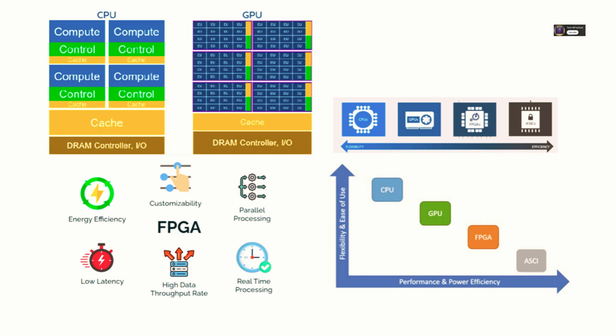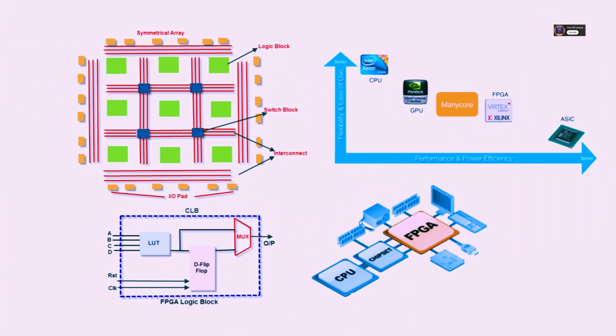Exactly. Those systems demand deterministic latency. They absolutely require the guarantee that the response will happen within a specific tight timing window, maybe microseconds, every single time, without fail. And the FPGA delivers that. Yes, because its logic path is essentially a fixed hardware circuit implementation for that task. It guarantees that real-time, predictable response. That's why FPGAs are often mandatory for critical signal processing. Think 5G base stations processing radio signals or automotive radar systems. That distinction, throughput versus predictable, deterministic latency, that's absolute gold.